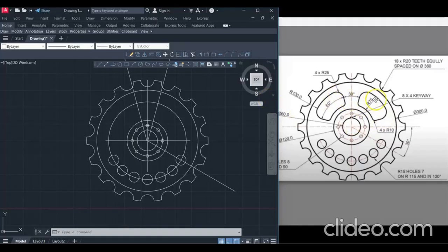Okay. Then what do I have to do later on? The included angle in between this is 60. Just observe carefully. This is a perpendicular in the second quadrant, right? 15 degrees we have already drawn, so what will be the remaining? 75. If I am able to draw a horizontal line which makes 15 degrees with respect to this horizontal inclined line, then my task is over. Automatically the included angle is 60.